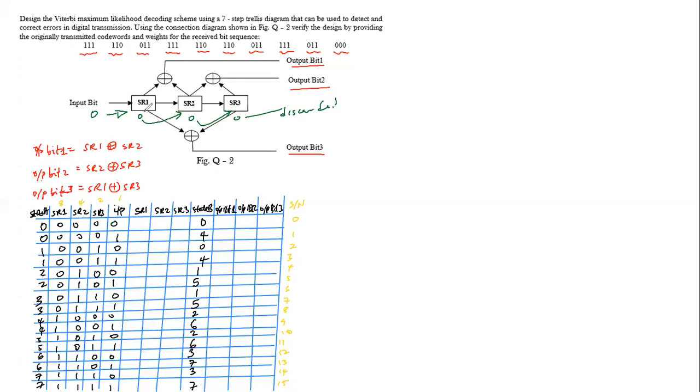So it means that in shift register 0, we now have the bit from the input, that's 0. Now, the original bit that was held in shift register 1 moves to shift register 2, so this now becomes 0. And that from shift register 2 goes to shift register 3, that becomes 0. And what shift register 3 held before is discarded.